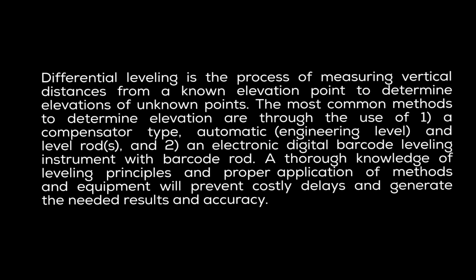The most common methods to determine elevation are through the use of number 1, a compensator type automatic or engineering level and level rods, and number 2, an electronic digital barcode leveling instrument with barcode rod. A thorough knowledge of leveling principles and proper application of methods and equipment will prevent costly delays and generate the needed results and accuracy.